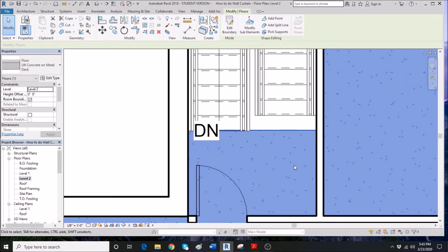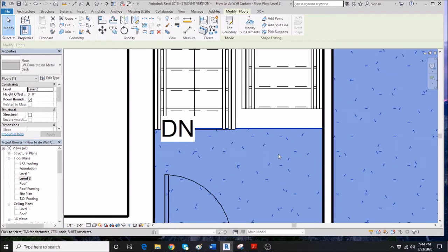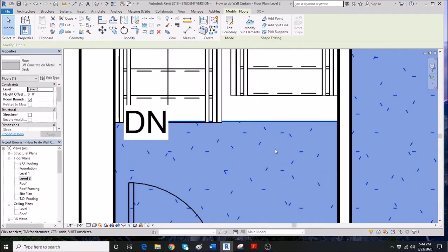With that, we are going to modify a little bit of your railings. What we want to do is create a boundary here because that's open, and to do that, you create the edit path of it. So select the inner railings.